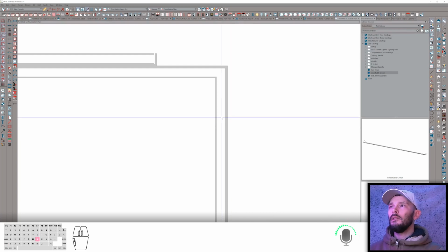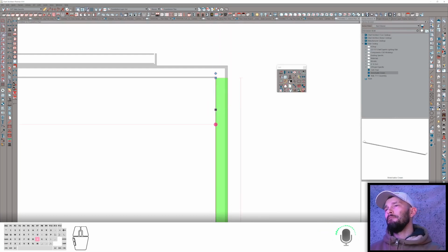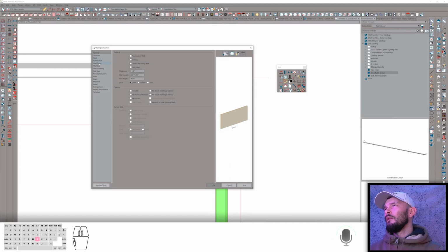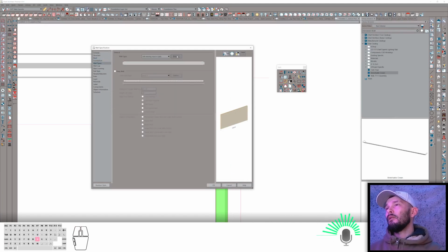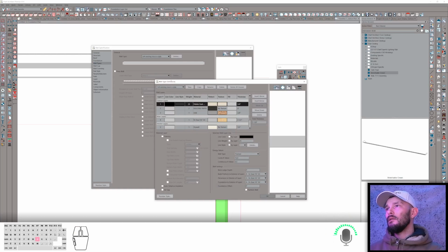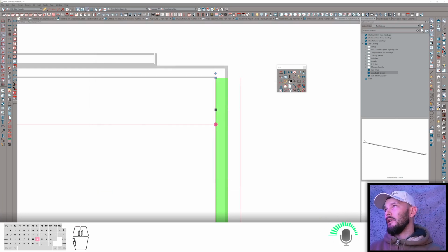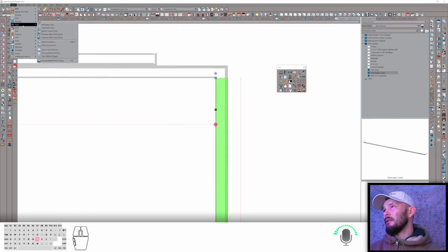So if I go up a level and I pick up my wall type, open this up, now I can set this to be a garage wall, and we could very easily make a copy of this and rename it, garage wall, for instance. And then foundation to the exterior of layer, there's where our foundation wall is, build platform to exterior. So this is more about how you want to align the foundation. But I think what we're talking about instead here is our actual footing.